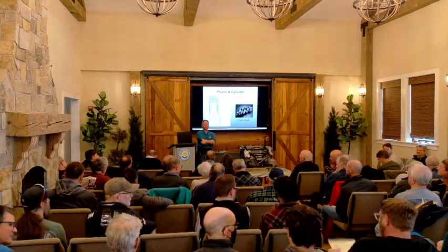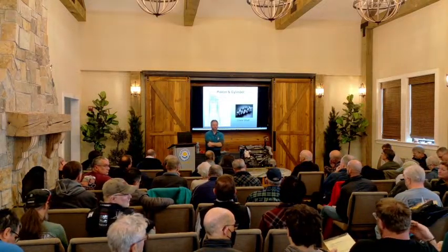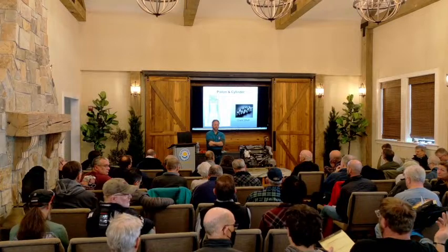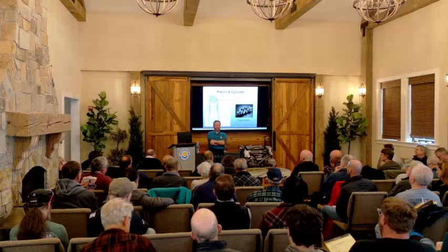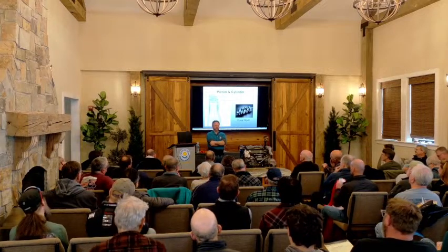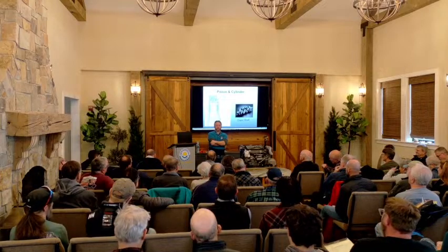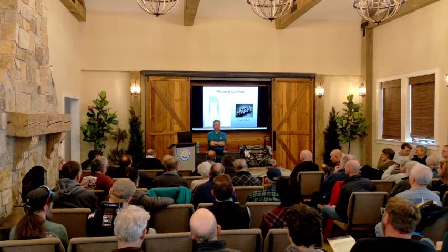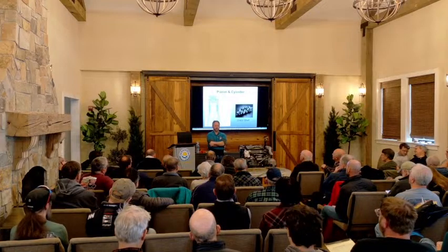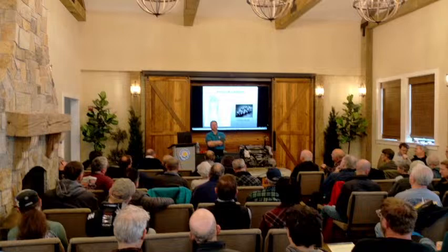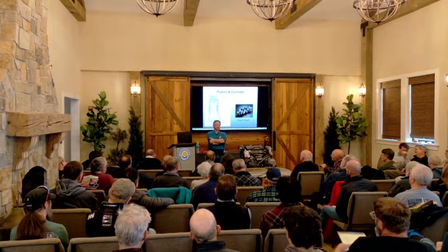You said I'll change the oil every 100 hours or once a season. If I change my oil, but I only run the boat like 6-7 hours that season, do I still need to change it at the end of the season, or is it good for the next season? That's up to you. Generally, if you get closer to 30 to 50 hours, we would say definitely. But if you only got 7 hours on it, it probably didn't need to be done. But if you still only have less than 20 hours combined in 2 years, change it. What about the 3-year fall?